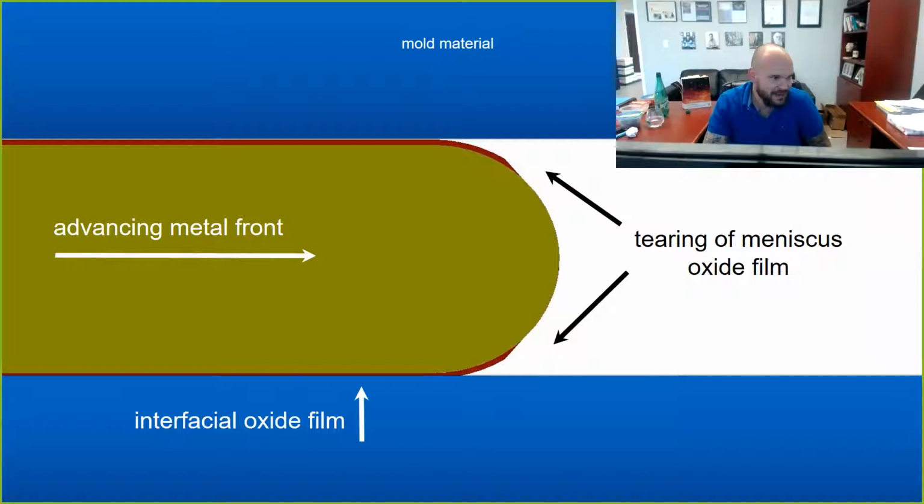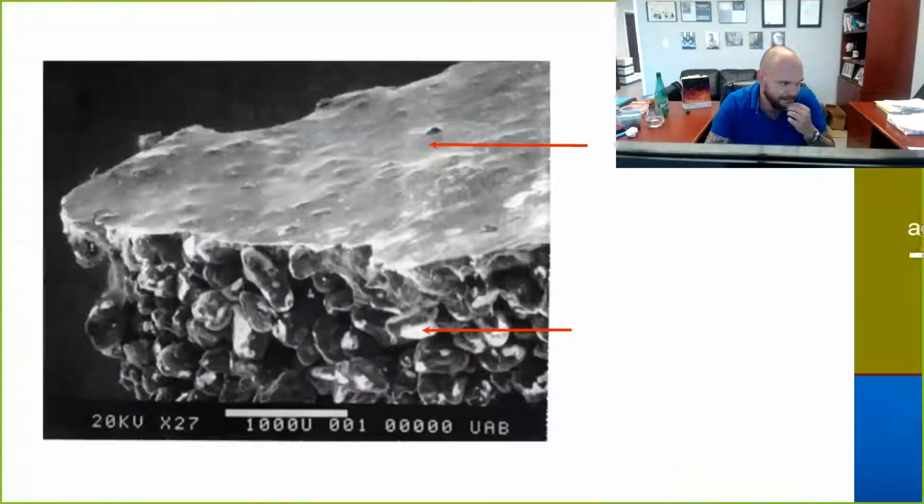And what happens now is we've got metal pushing all the air forward. So we've got a beautiful, beautiful setup where even if there's dirt in your runner because something broke off when you close the mold, the metal's just going to run over it like an ATV and an Argo, like a tank trap. It's not even going to matter because it's not going to get in the melt. The metal's just going to run right over it, bump, bump, just like it wasn't even there. And now we have an opportunity to start creating beautiful castings.